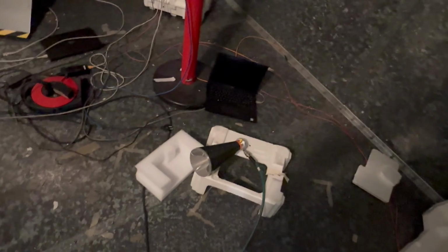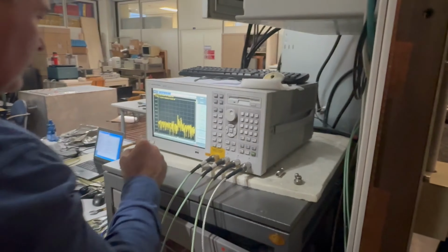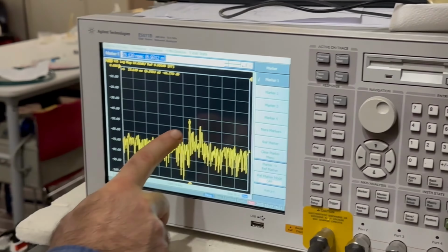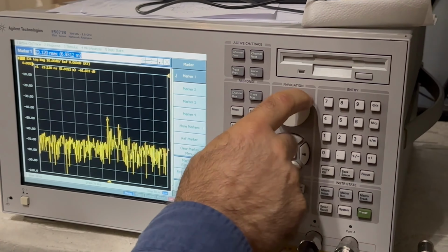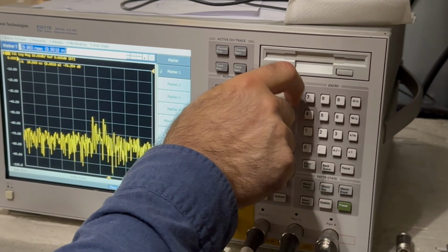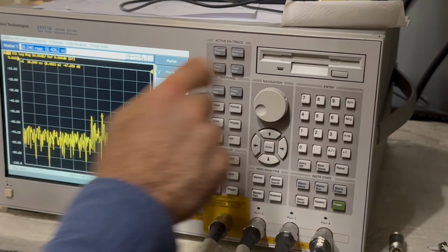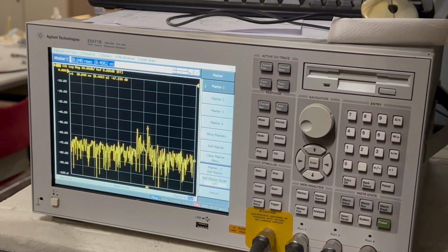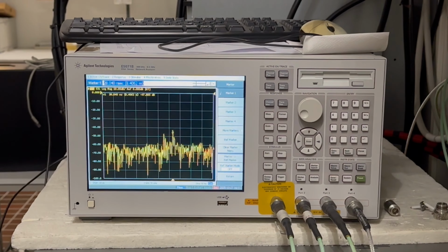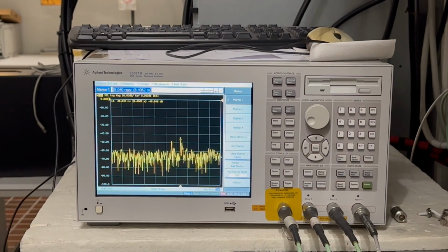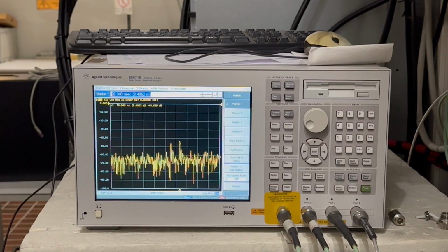So now we rotated one of the antennas towards the wall and the steerer rather than directly pointing at another antenna. We see that the PDP changed. For example, I think that this is the back radiation, yeah, first, and the next peak is due to the reflection of the main wall. This is the main wall. Okay, some peaks grow and then decrease depending on the steering position. Okay, what we didn't see before.